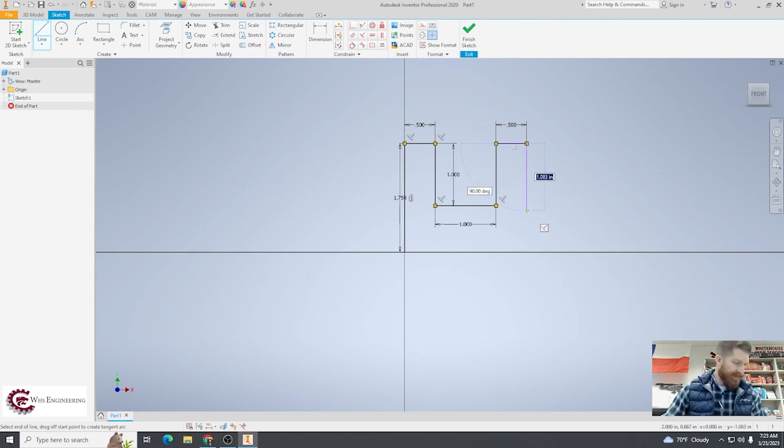down, 1.25, and this will be 2.5. Down, and then this is very important. A lot of people forget to do this. You've got to close your geometry. So I've got to take this line and go back here and close it. If I don't do that, I don't have a solid. If it won't hold water, you're not going to be able to extrude it.